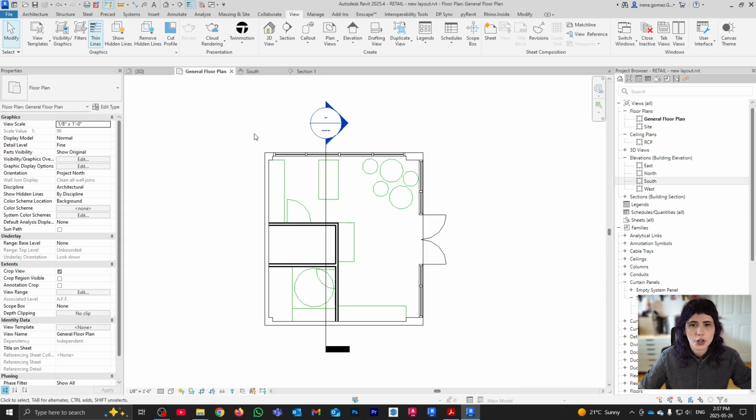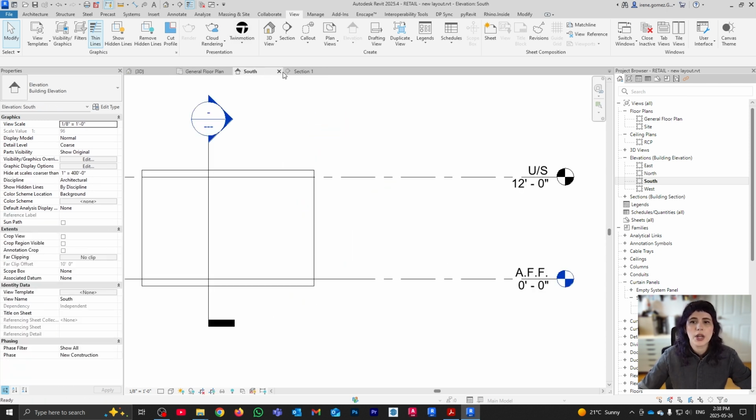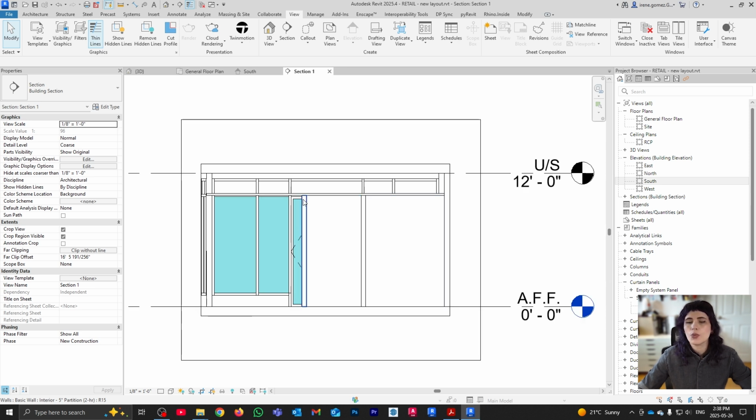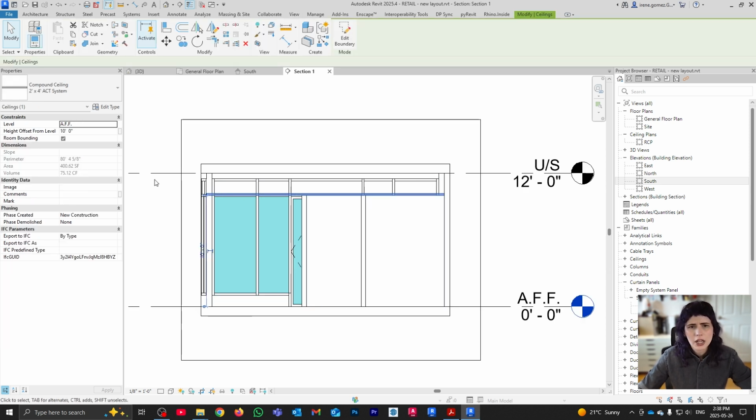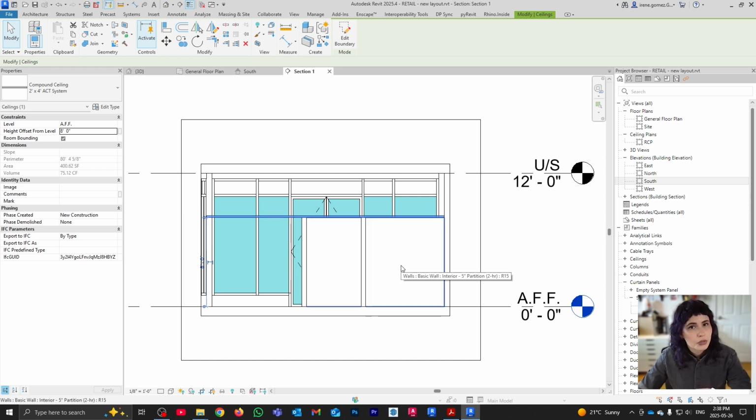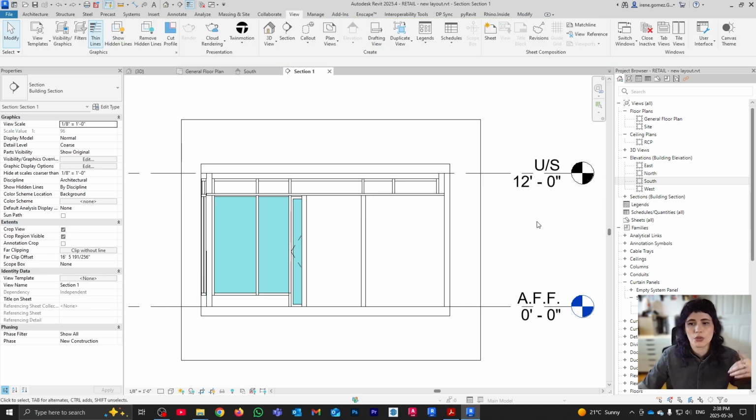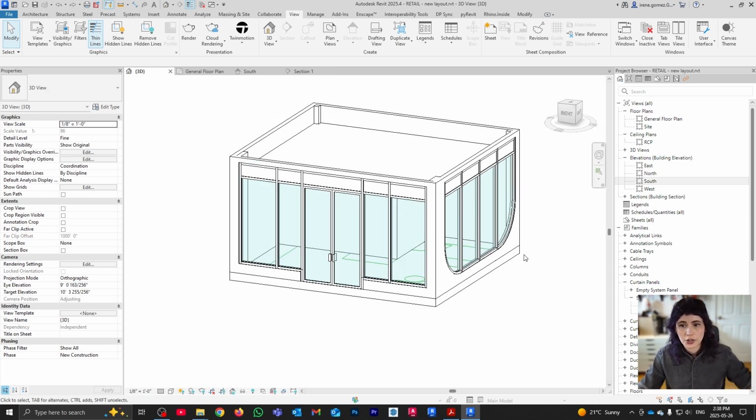If you want to be even more hardcore, after you do that, you could lock it. So that way, if you ever change your ceiling height, it will automatically change your wall height. But if you align the top to bottom option, you automatically lock them. So check it out. If I go here, 8 feet for example, see, now my walls follow. So remember, being parametric is the most important aspect of your Revit geometry. You don't want to change one thing and then have to enter this panic mode of like, oh my God, what else is affected by this change? What am I forgetting? You want things to be related to each other. And that's pretty much it.